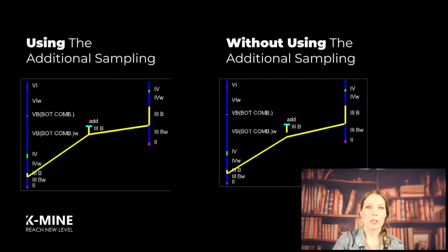With additional samplings applied to the selected type of workings, the actual positions of the top and bottom of seam intersections are taken into account. For example, on the left figure, the bottom of guide seam 3B, the blue line, is shown when the drill hole add is used as additional sampling. In this case, the algorithm directly considers the actual intersection of drill hole add with the bottom of guide seam 3B in 3D space, without interpolating the seam thickness based on adjacent drill holes.